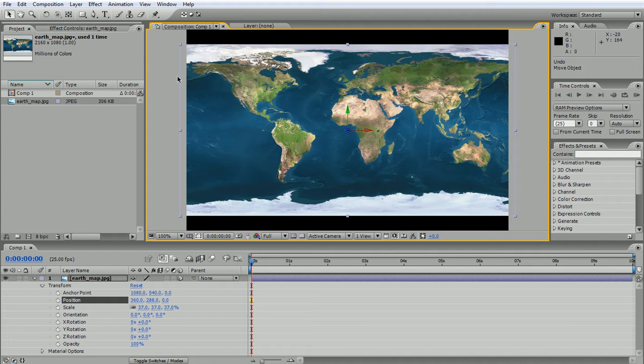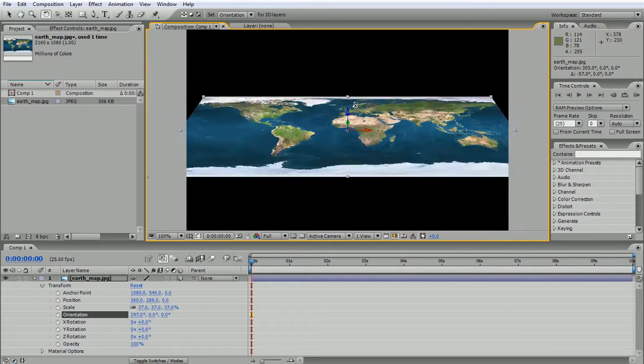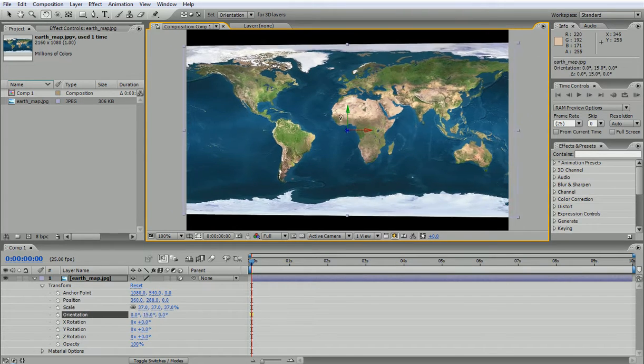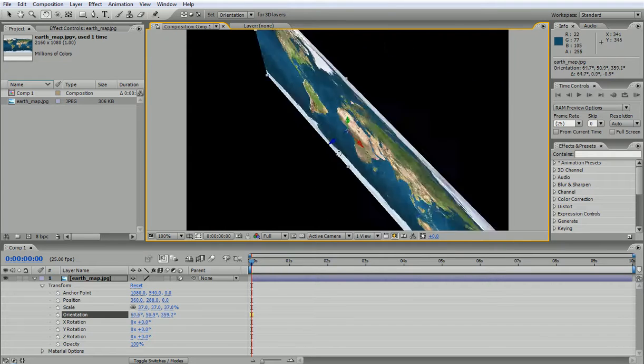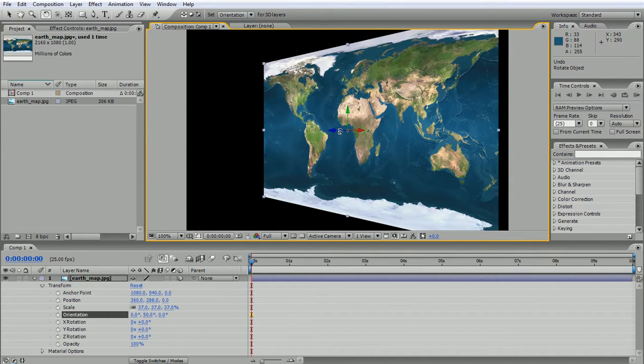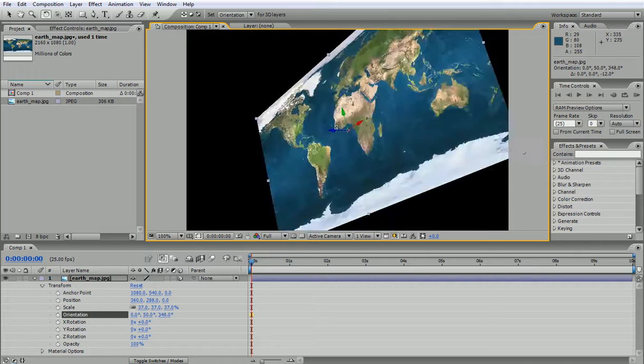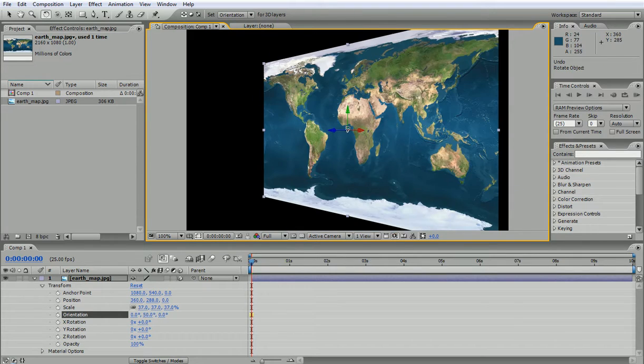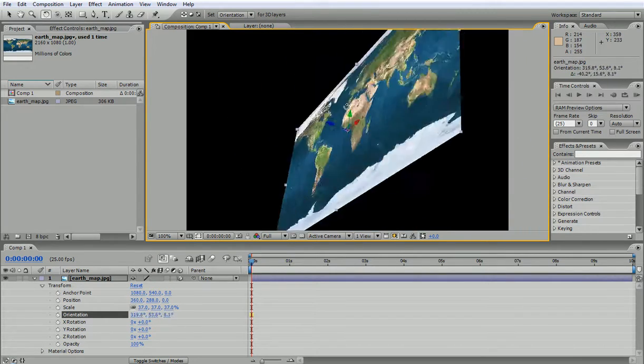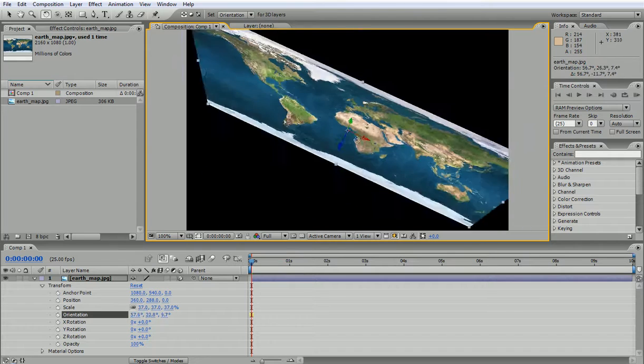Once I create a camera, I'd be able to rotate like in 3ds Max. But if I go to rotate object now, I can rotate around the X-axis like this, around the Y-axis, and around the Z-axis. So that's freeform, but this is around the Z-axis. If you rotate from the center, from here, you rotate in freeform mode.